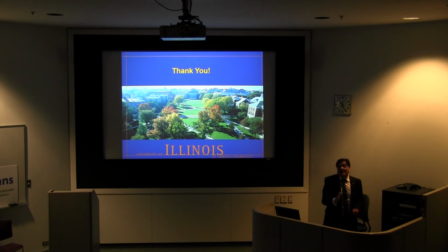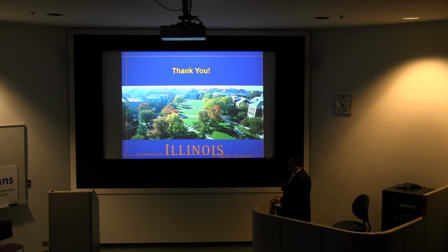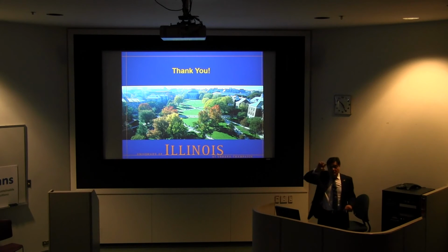As I told you, this is not an X-ray. And I gave maybe an example. If I have two materials that have completely the same dielectric constant, I will not be able to see them. However, which I did not present here, sometimes we deal with asphalt concrete that has different layers. So the one on the top has a different aggregate size than the one underneath it, maybe 1.5 inches, and then you have maybe 2 or 3 inches. They have different aggregate size, and accordingly, they will have a different asphalt content, but they have the same air void. Now, the dielectric constants between these two could be maybe 0.5.